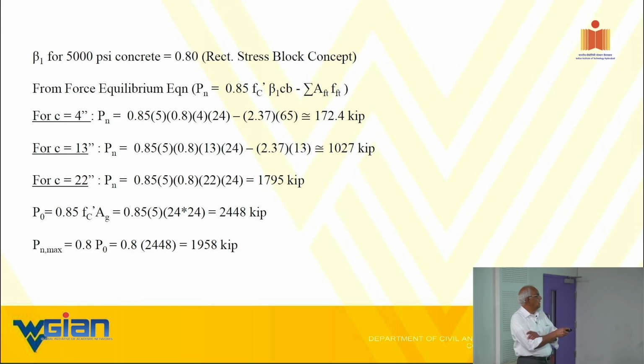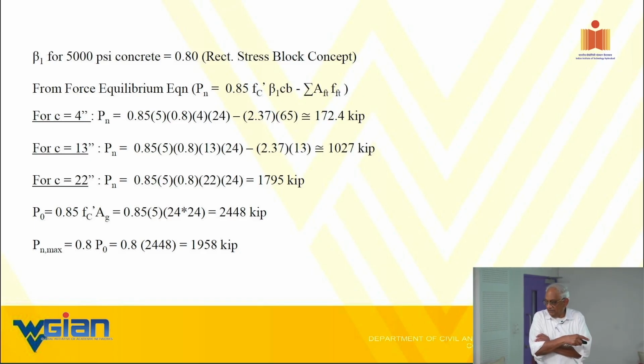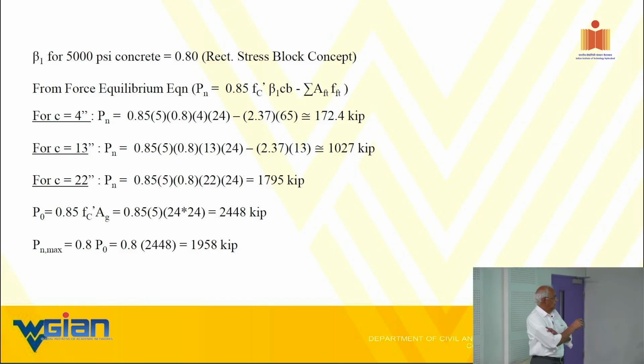Here we did not subtract because it crossed the... Here it crossed, exactly right. You remember I said we exceeded the 22 inches, the neutral axis. Therefore, it went into the compression zone. Therefore, we are not accounting for that. That's the point. Good catch. Then I multiply that with our phi factor, effective, and that is the maximum value.